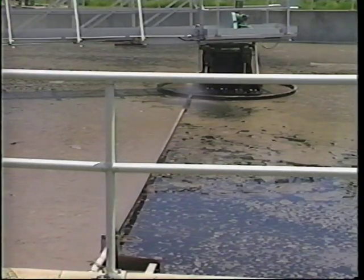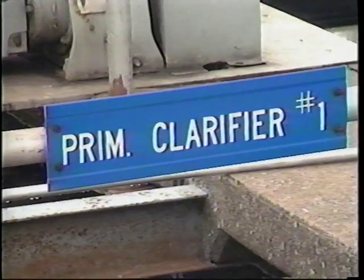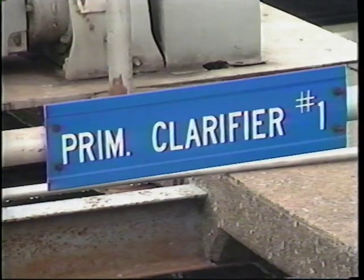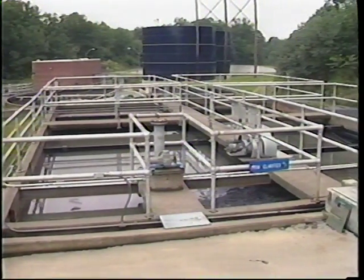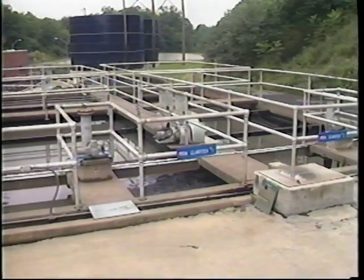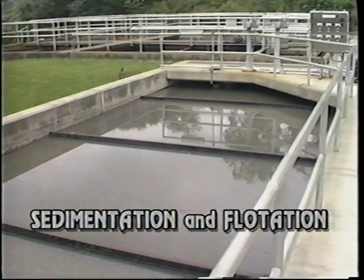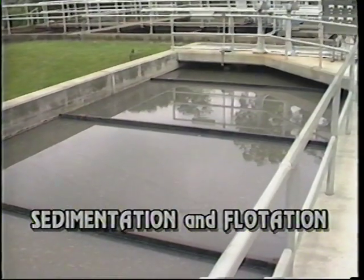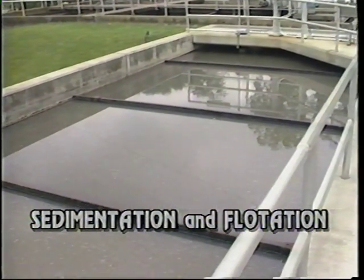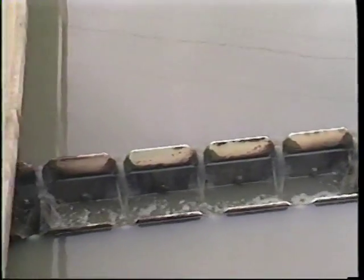The process of removing settleable and floatable solids from the wastewater is usually accomplished with a treatment unit known as a clarifier, which facilitates a process called sedimentation and flotation. The main job of the sedimentation and flotation process is to remove settleable and floatable solids by greatly slowing the velocity of the wastewater while providing a placid environment where many solids will either settle or float. After the solids settle out or float to the surface, the clarified wastewater flows over the effluent weirs onto the next stage of the treatment process.